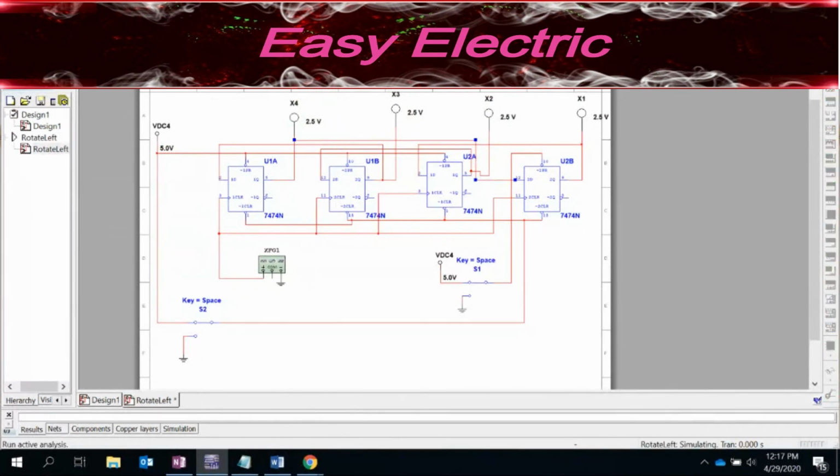So let's start the simulation. In the beginning, I just activate the initialize for a short time, 0, 1, so everything is 0, right? This is shift left with rotation, but because everything is 0 here, we couldn't see anything. So let's make a 1 here: I put 0, make 1 and back to 1. Then you can see this shift left and rotate back to here. In the next rising edge it is here, in the next it is here, okay? As you can see, it does that, and again goes back to here as a rotation. So the design works, and it is the shift left with rotation.